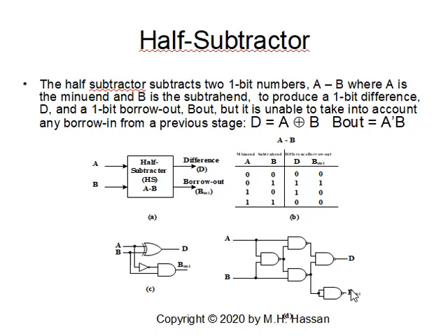It is super easy. It is very simple. We have two 1-bit numbers, and we get the difference d and the borrow out, which is b out. There are no simplifications to those equations, so we don't need K-maps or Boolean algebra at all. We can define d and b out and implement them simply, either with an exclusive OR, inverter, and AND gate, or with 5 two-input NAND gates.